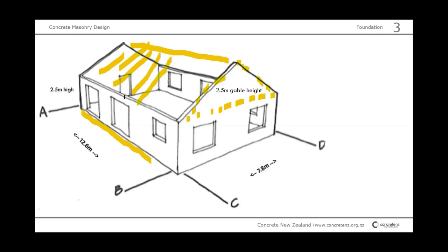So what are the loads here? What are the loads there? And then again, 4229 keeps it simple. Whichever load is higher will govern for the entire building. Let's say if you have 15 kilonewton per meter here, maybe 18 kilonewton per meter here, then we would assume there would be also 18 kilonewton here. So the foundation is always governed by the higher load.